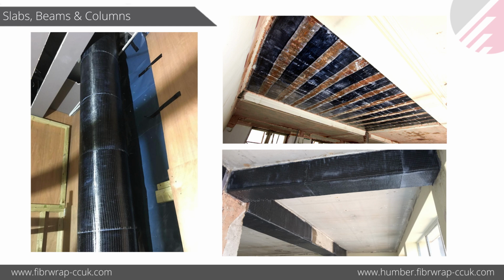We also do wall strengthening for new services or other penetrations and everything. But from a technical point of view, these are the 2 types of application we do. So slab strengthening, beam strengthening, we are relying on bond between FRP and concrete. So that's why they are called bond critical applications. Whereas in a column strengthening, where we are confining a concrete element like a circular column or something, we rely on contact more than the bond. So the bond doesn't matter that much, but the contact matters.